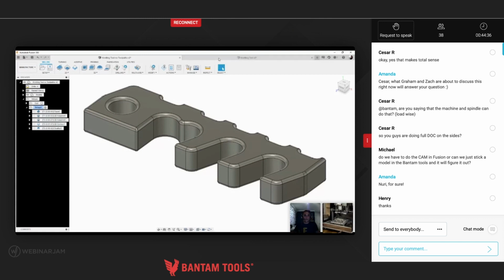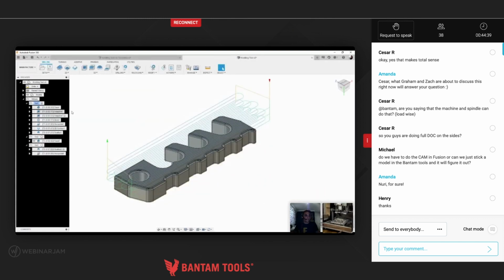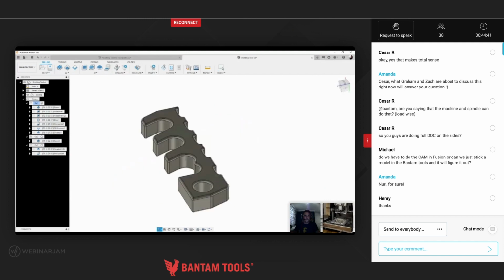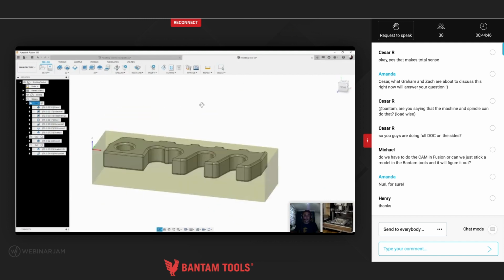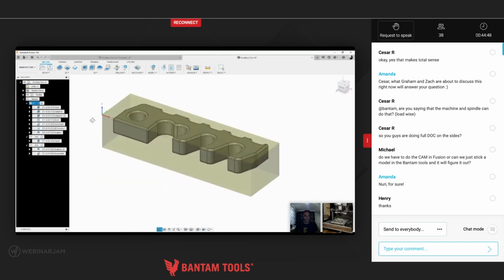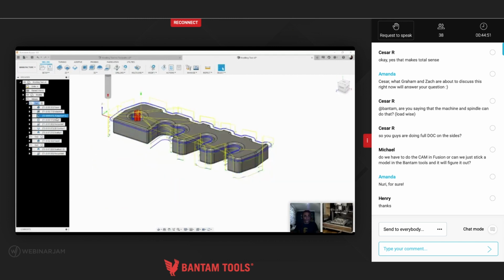So if I just quickly jump to, here's what I did earlier on my toolpath here. You can see we've got a whole operation, sort of a single setup here. Again, similar practice with our setup in the top left. There, with our adaptives, a boring operation to cut this part out of here. Horizontal toolpath, which essentially just cuts lots of flat surfaces to tolerance. It's a finishing toolpath, can be used as roughing, but it's a great toolpath because most of the time, like a facing operation, you can just press horizontal, OK, and it'll machine all the flat surfaces. So down to our scallop.